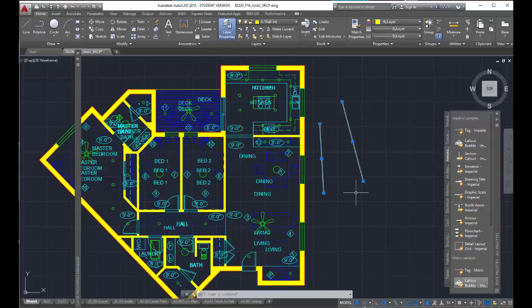Now you might be thinking, this is all great, but how am I actually going to use all of this? You're going to use it when you're drawing your floor plan. You aren't going to want all your layers turned on when you're drawing. So for instance, when you're hatching ceilings, you don't want any objects in the middle of your ceiling, so you need to turn things off like the furniture and the casework and such. You're also going to use these when it comes to working with the sheets that you draw in paper space.